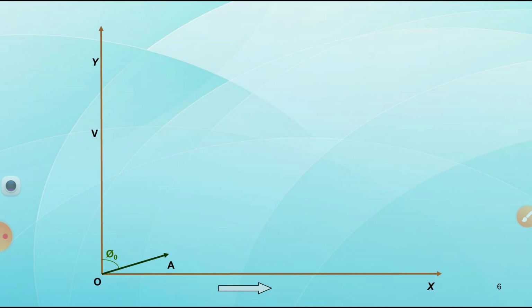Now, what is the second step? In the second step, you take the short circuit current. I know the phi SC from the blocked rotor test, and I know the value 0 to B, magnitude ISN. Okay, I take that ISN. So 0 to B we take it. Now we have the magnitude 0 to B and the angle phi SC from the blocked rotor test.